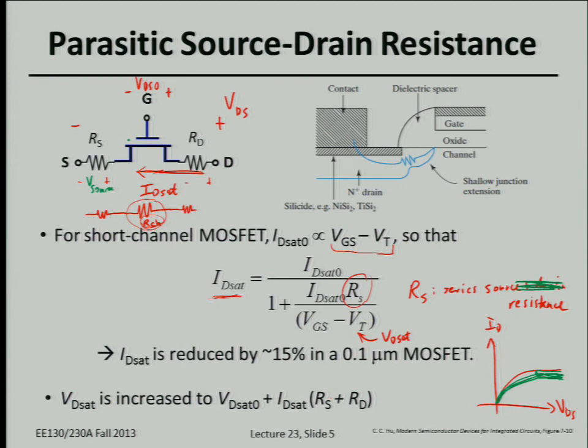Okay. Now, on the previous slide, I also showed the tungsten, let's say the typical tungsten contact material. And here's the silicide. So the typical silicide today is nickel silicide. So you can say, well, okay, and this is a practical issue, we can actually just make the silicide thicker, right? We can react more metal with semiconductor to make this silicide thicker, to reduce the parasitic resistance, right?